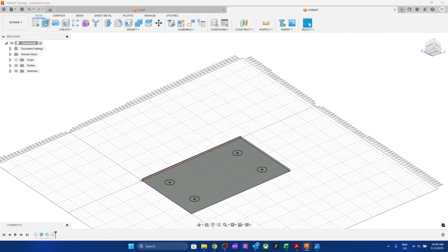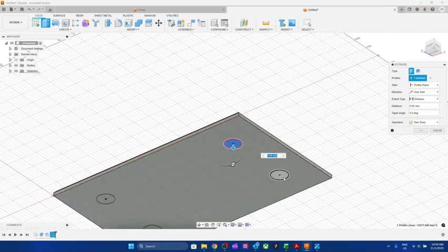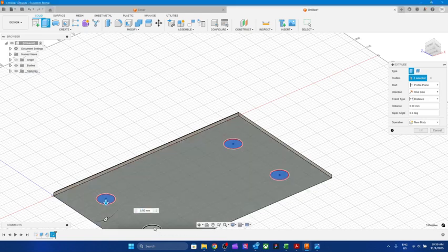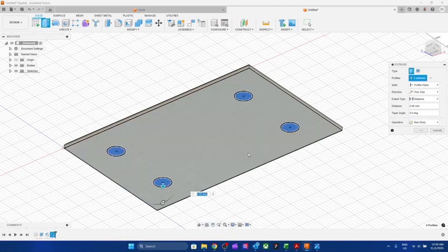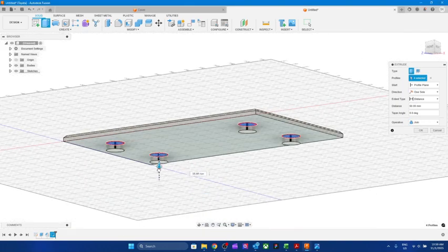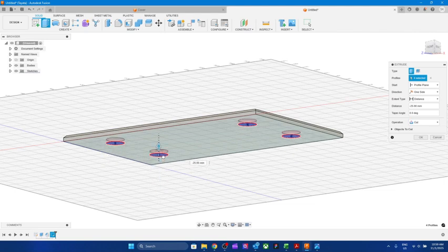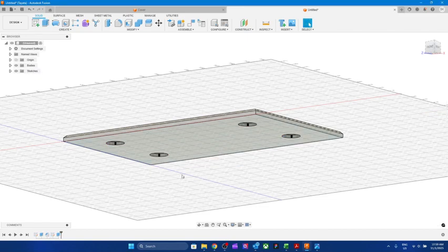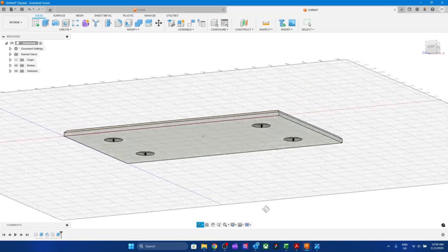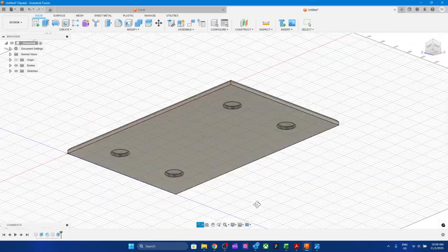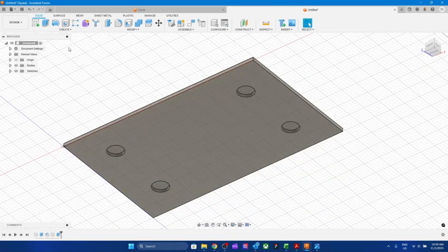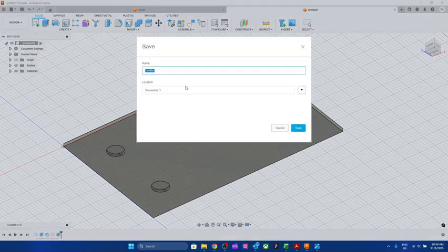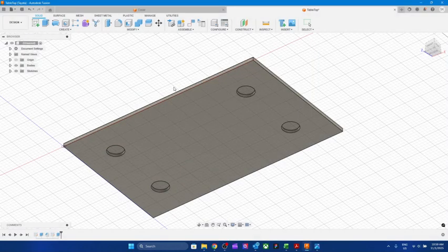and now I want to extrude. Select, select, select, and select. I've selected all of them, and see it's coming out, but I don't want the legs like this. I want it inside. It's going to be minus 20 because altogether the size is 40, isn't it? Yeah, the thickness, and that's why I have kept it 20, so halfway through the tabletop. So I will save this as a tabletop. So tabletop, save.